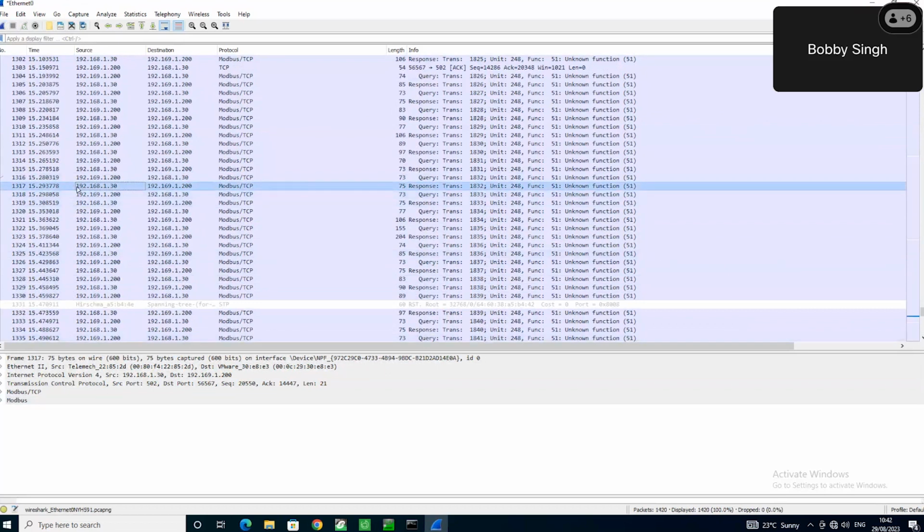So as you can see on the network, it's completely exposing the IP address of my VFD, since Internet Protocol security is disabled. So I can see the IP address of my drive that's on the private distributed I/O network. And I can see the IP address of my engineering workstation, which is fine, but you do not want to see the IP address of the VFD.